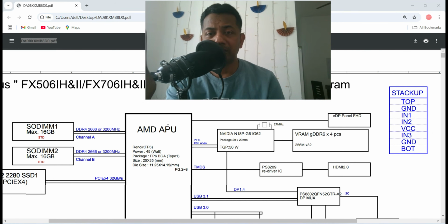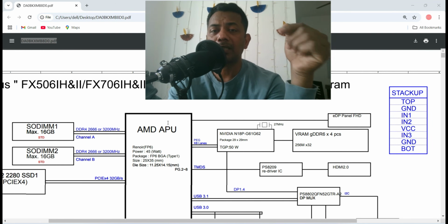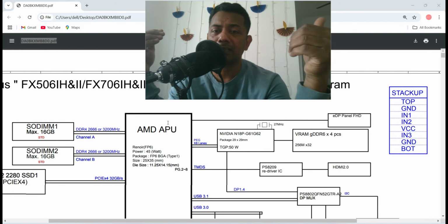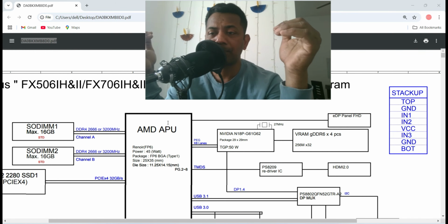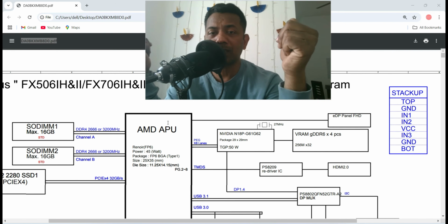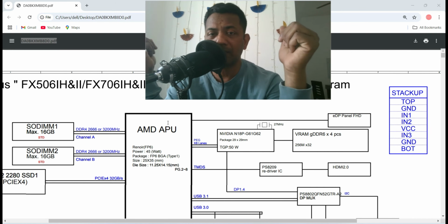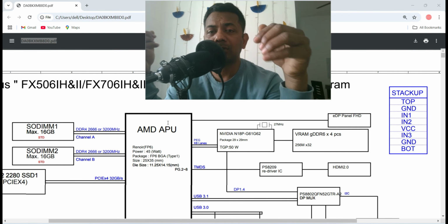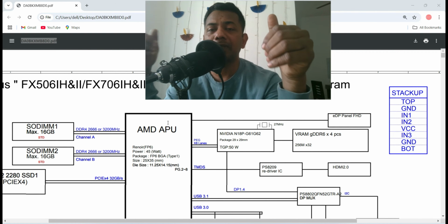The main short will happen when the voltage is connected to the ground. It means we are not getting any voltage because it is directly connected to the ground, then the amps will increase, and you will get a short. In the second condition, the particular connected device won't work. In that case also we can call it a short, or just not working. But don't simply judge, you have to thoroughly examine, and only then decide why it is a short and where exactly we need to check.